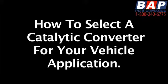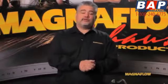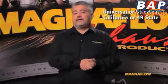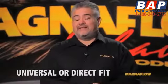In order to select that right converter, we need to consider a few things. First of which is the type of converter, whether the person is going to need a universal or a direct fit. Then to consider the application, is this going to be on a California car or a 49 state based car? And then ultimately to determine the right grade of product based upon the application.